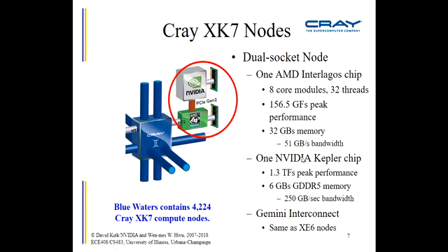However, the memory bandwidth is only about 5 times more. It's from 51 gigabytes per second to 250 gigabytes per second. For those of you who are familiar with Pascal and Volta, NVIDIA adopted a new technology called high bandwidth memory, HBM. And this is exactly the reason why they did it.